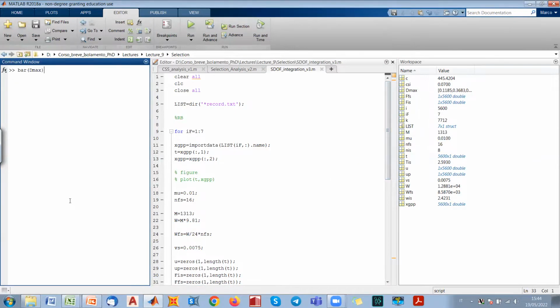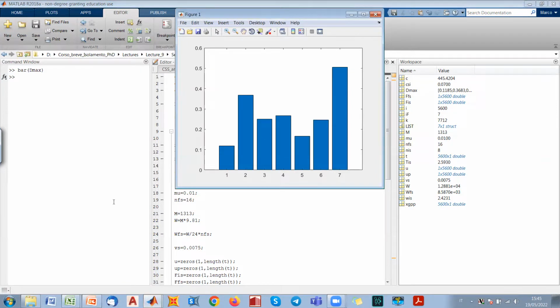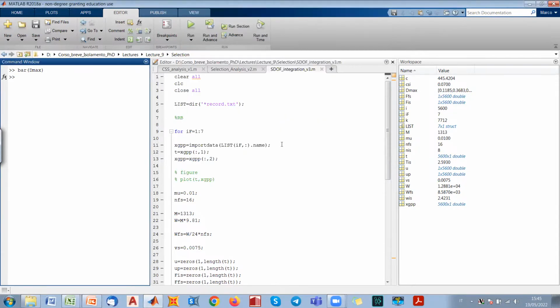So let's check the bar plot for the maximum displacements. Okay, so we have something like this. So maybe we are about here, something less than 300 millimeters. Let's check. Mean, yeah, 274 millimeters. So a little bit lower. So this is actually good for us if we design isolation devices which have the displacement capacity higher than what we obtain from the assessment. This is good. It could be worse if we get exactly the opposite.